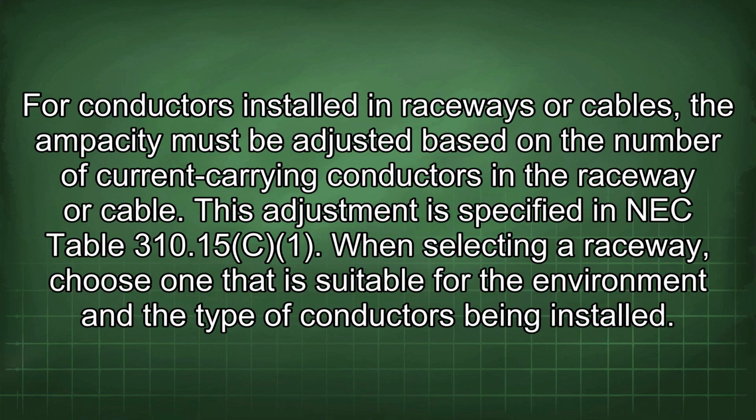For conductors installed in raceways or cables, the ampacity must be adjusted based on the number of current-carrying conductors in the raceway or cable. This adjustment is specified in NEC Table 310.15. When selecting a raceway, choose one that is suitable for the environment and the type of conductors being installed.